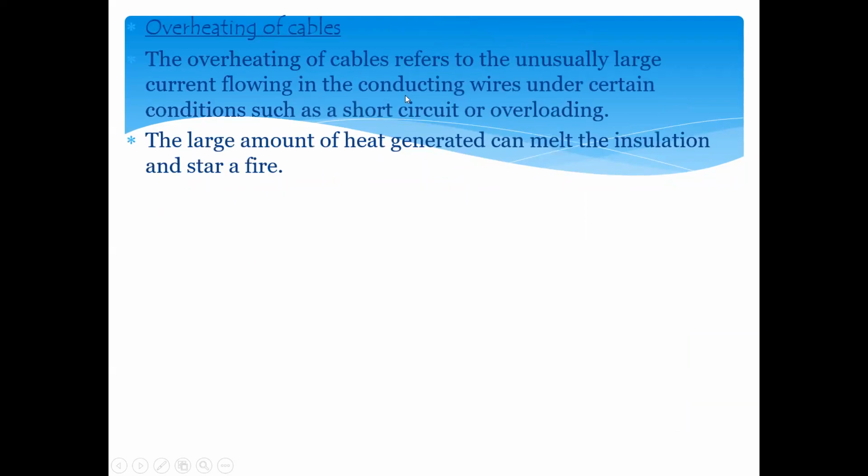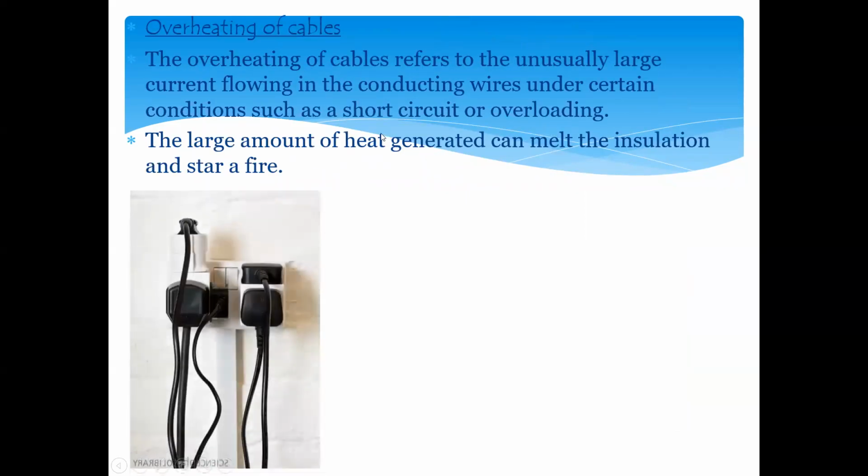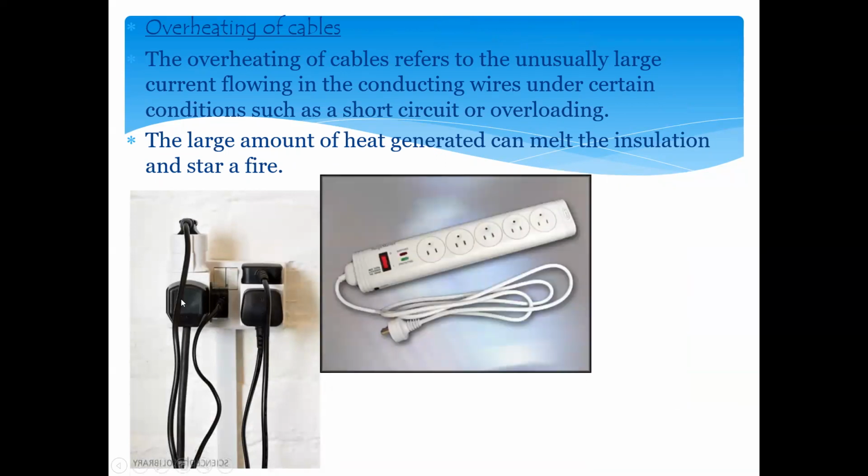Second thing is overheating. This is very common in our home. We are connecting a lot of devices to one socket. That is not the right way of using electricity. That will lead to what? Whenever we consume electrical energy, it produces heat as well, and that heat can cause a fire. So this is not the right way of using electricity. Even when we are using extensions, that is also a source which might lead to a fire, because from one plug we are using multiple devices.